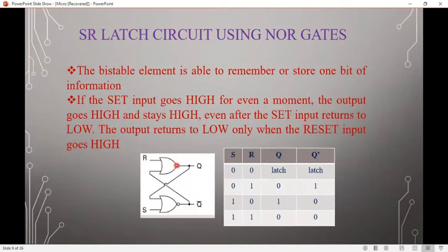SR latch circuit using NOR gates. The bistable element is able to remember or store one bit of information. If the set input goes high for even a moment, the output goes high and stays high. Even after the set input returns to low, the output returns to low only when the reset input goes high.